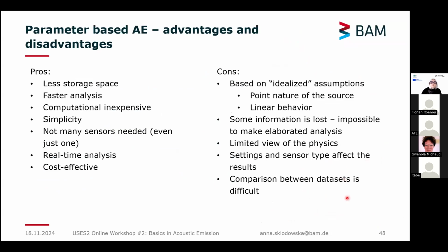Okay, so just to give a brief overview of parameter-based acoustic emission, there are some advantages and disadvantages. The advantage is definitely that we need less storage space. It's a much faster analysis, which also indicates that it's computationally inexpensive. It's very simple and does not require a lot of sensors. In some cases, even just one is enough to perform the analysis. It also gives real-time analysis, and it's cost-effective.